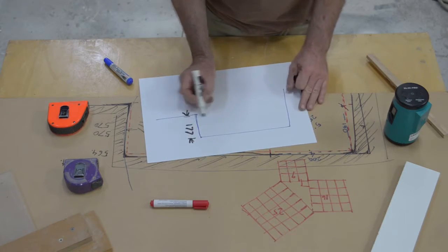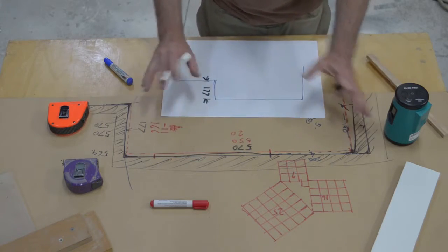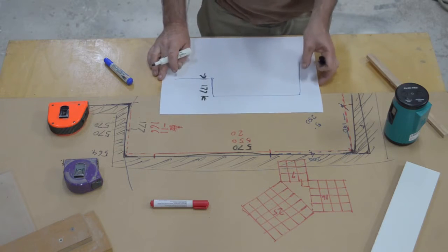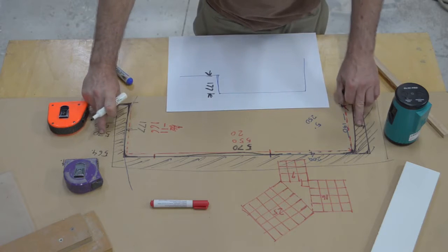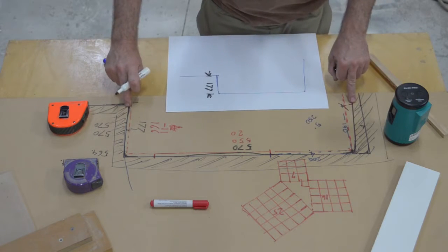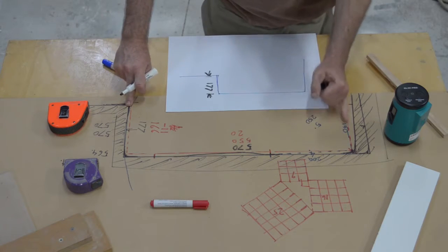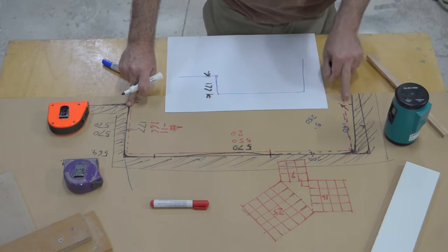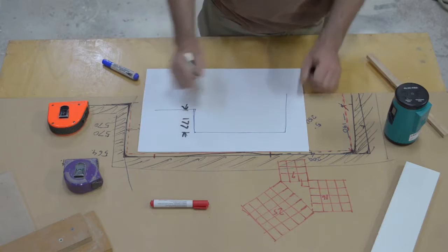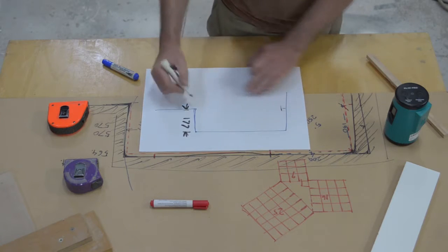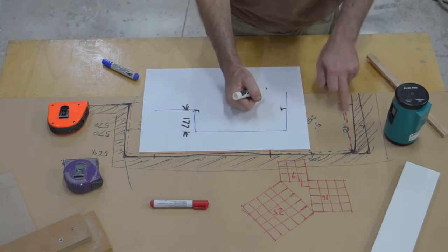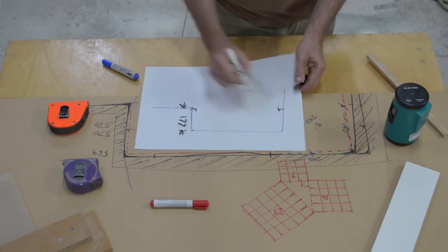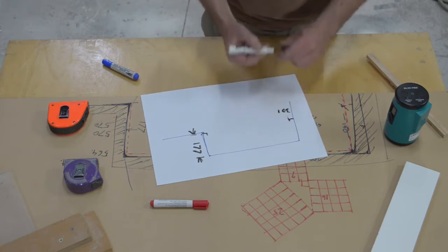But what I will have is the cabinet itself is going to be designed to be 150 because of how I naturally work. Okay, the width there is 570. Oh, sorry, here was 570 at half depth and the front edge was 570. But I did go through the process of assessing that it wasn't square. Either way, it was telling me there's some fishy business over here. So I'm going to build in a 30mm infill on this side. And the same there. Just because I saw, even with my little Pythagoras method, it alerted me to the fact that there was an error here. So I might make a note, 30 infill. No, terrible.